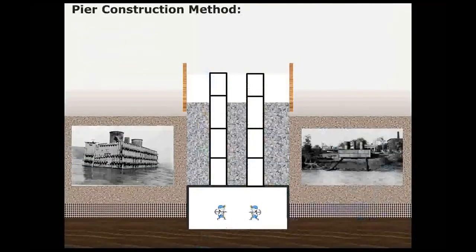So this, if you'll recall, Aaron's presentation about how those caissons were constructed. They lowered down a steel chamber that they used to excavate the material at the bottom of the river down to rock. And once they reached the bottom of the river, they filled up both the access tubes and the chamber with concrete. And we thought maybe the voids we were encountering were related to that steel chamber.